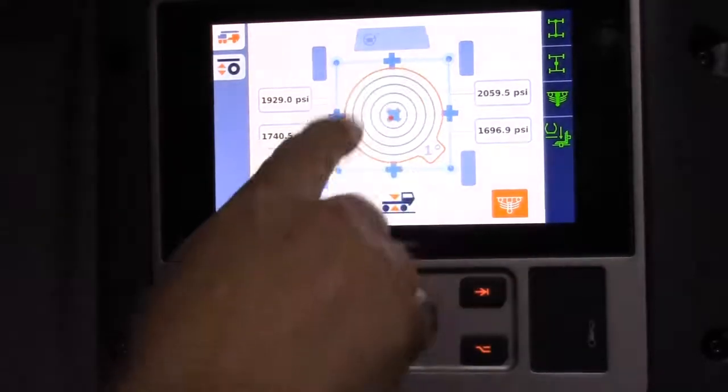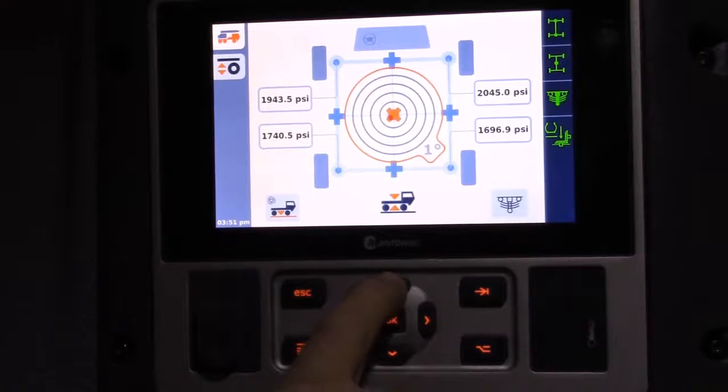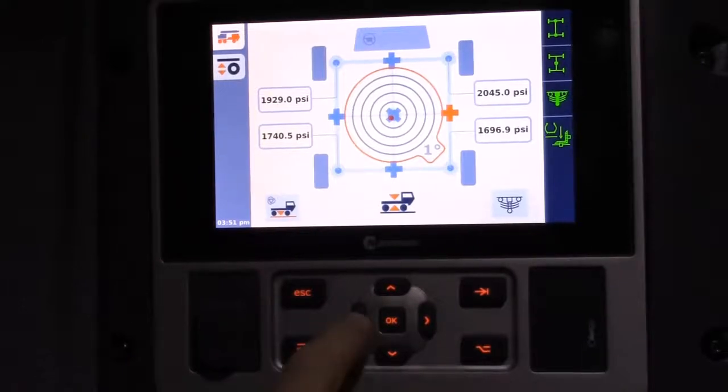indicator items here that tell us the different suspension groups. The GMK4100 has 4 suspension groups. So we have the ability to select the front suspension group, left side suspension group, rear suspension group, right side suspension group, and then the middle icon allows us to select all 4 suspension groups, thus allowing us to raise and lower the suspension of whichever group we decide to pick.